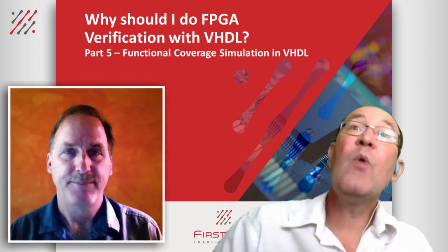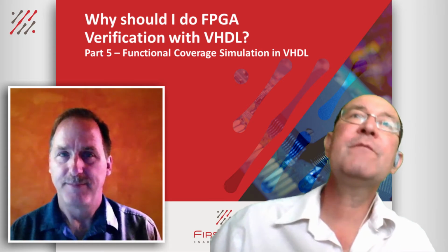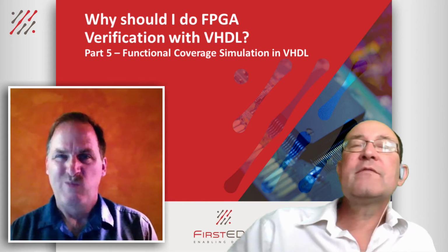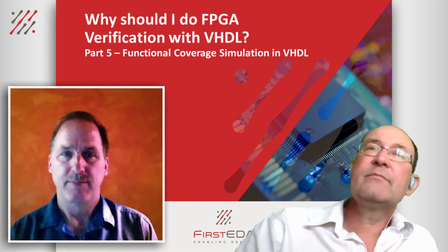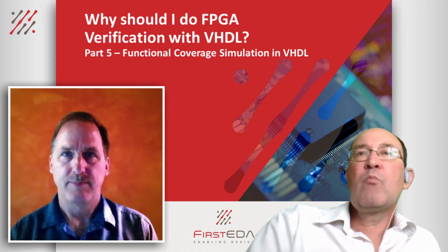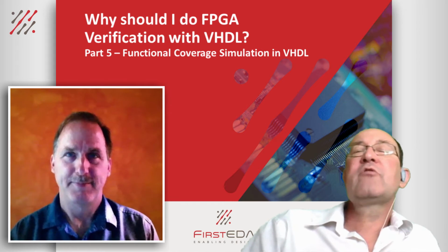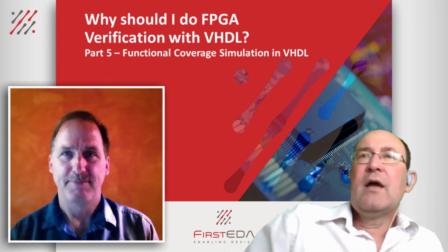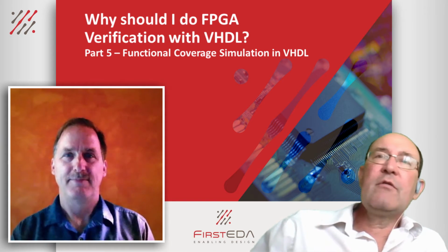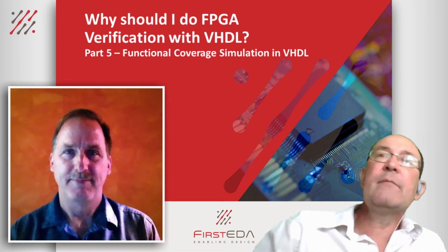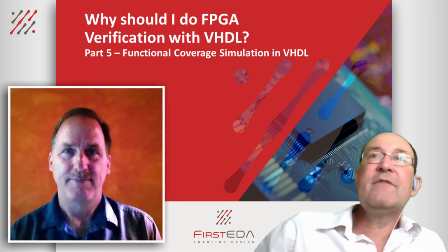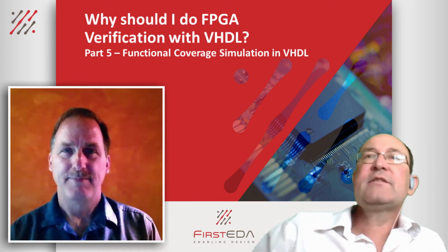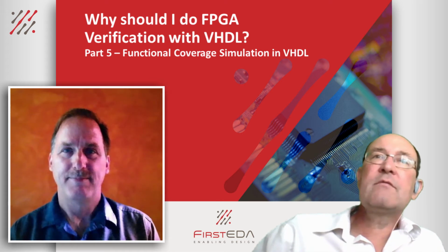Thank you, Jim. Very interesting, as always. And I think that rounds off the methodology quite nicely. We can drive random stimulus into our designs on the interfaces of those designs using constrained random stimulus and capture the coverage within the coverage model to ensure that we're actually testing to our test plan. So it's a nice methodology. And on top of that, everything I've seen, it's standard VHDL, so it's not that much different to the RTL I'd be using in my FPGA design. So it seems that it's very easy for RTL designers to pick up the methodology and start writing powerful, comprehensive test environments to test their designs. So that's a double bonus.